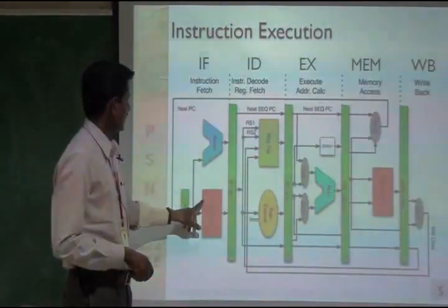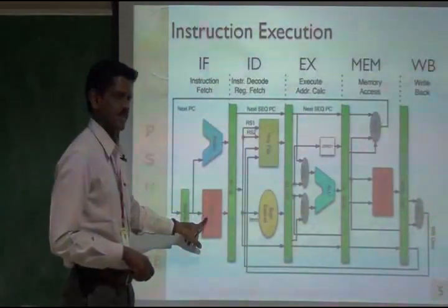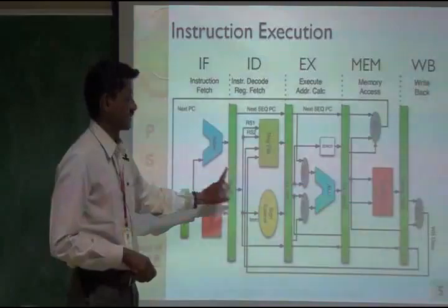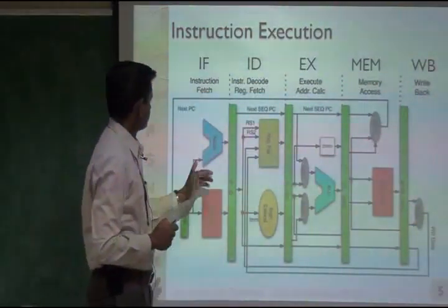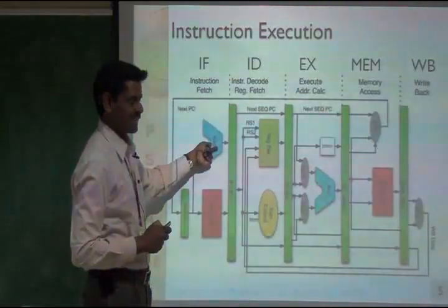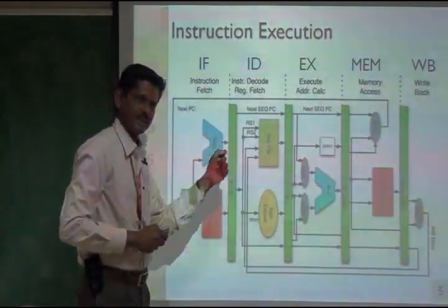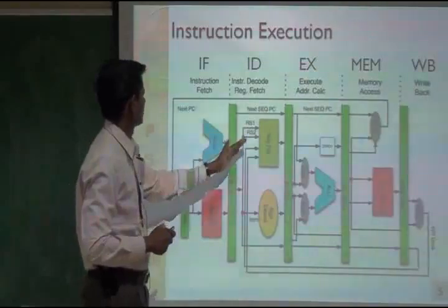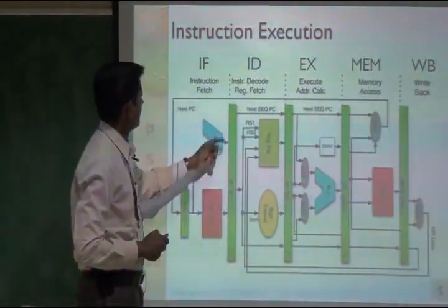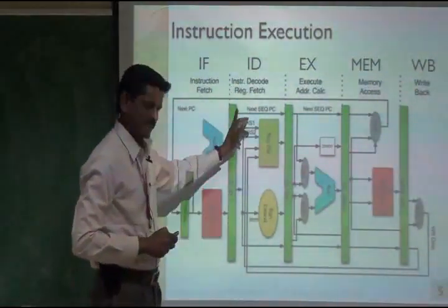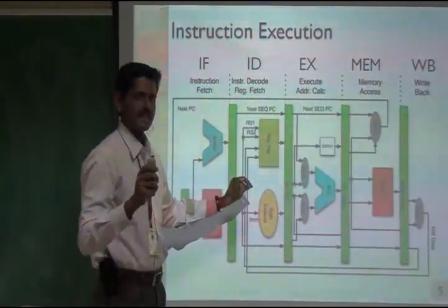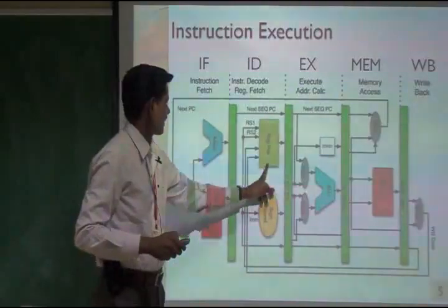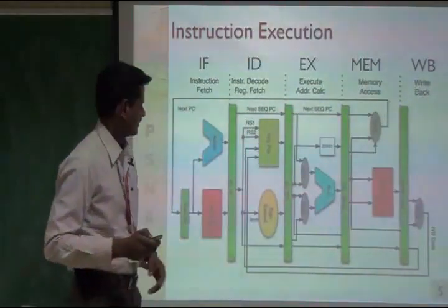Using the address, it finds the location of the instruction and does the fetch operation, that is stage 1, instruction fetch. Then the PC is automatically incremented, so it can locate the address of the next instruction. Now come to the second stage, decode. It decodes the instruction as well as reads the necessary register operands that are available here, register 5.